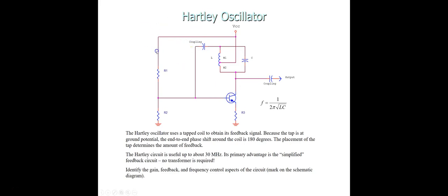And then we have here a band pass filter. This C and this L form a band pass filter, and again it controls the frequency of the oscillator. So this LC tank formed by this L and C is a filter, and only frequencies close to resonance can get through the feedback filter. So the circuit can only oscillate close to the resonant frequency of the LC tank.